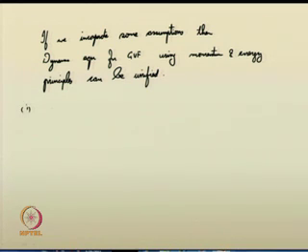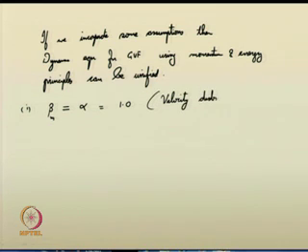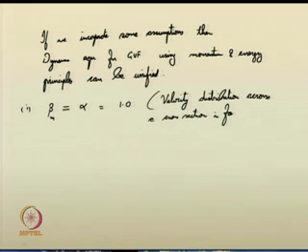Say, if you assume that the momentum correction factor beta_m is almost equal to the kinetic energy correction factor alpha, and they are almost equal to 1, say we are approximating it as 1 if there are no significant correction factors involved. This suggests that the velocity distribution across a cross section is fairly uniform.